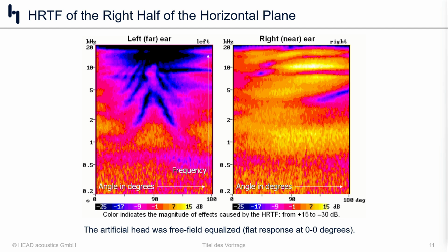On the same side of the head where the loudspeaker is, you get a big increase in level at the higher frequencies, especially above 1500 hertz, with a completely different complex pattern. So if this is mapped from black at the lowest level you get from the HRTF, from this broadband flat source, to the highest level you get, it's minus 30 to plus 15 dB. That's 45 decibels. Consider that listening to tonality in an electric vehicle, you have unavoidably a human perceiver, if you will, and an extremely different response according to the direction of incidence.